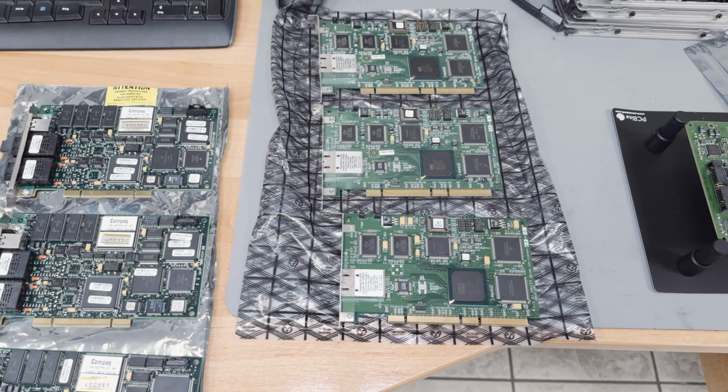You can see these are PCIX controllers, so a 64-bit connection. And here is one fiber connector, a 1G Fibre Channel connector, and they are called KGPSA-CY, but this is the typical DEC naming. K stands for storage controller, G for Fibre Channel, P for PCI. I do not really know what S stands for, but I think it stands for single, because it's a single connector, and A is the revision or generation.